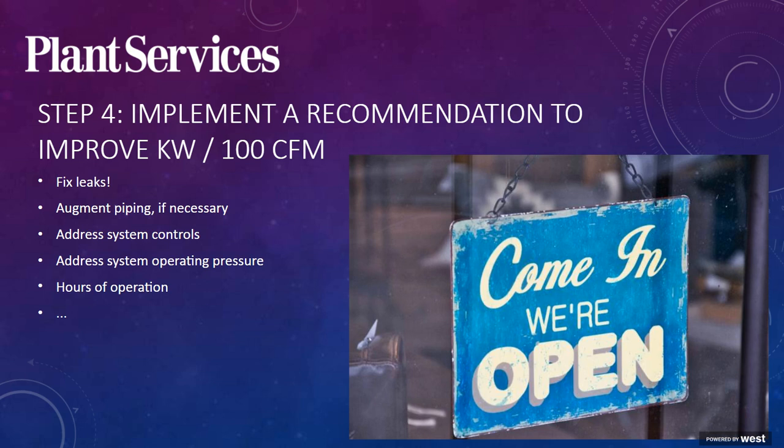Simple, easy, and something that may be often overlooked. Turn it off. It's just like I tell my kids when they leave the room, turn the light off as long as your sibling's not in there, but nonetheless, turn the system off. We established that energy cost for a compressor is 3/4 of the overall life cycle cost. We also talked about that compressors are as much as 10% of all electrical energy generated in the U.S. So why run a compressor or a system if you don't need to? Look at your overall production schedule. Simply turn off your station when it's not needed. That's going to save you a lot of money. And we're going to see that here in this example as well.